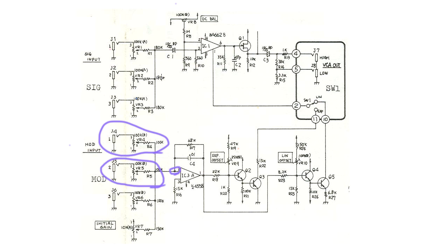I don't get weird effects such as the input impedance seen at J1 changing depending on what's happening at J2, etc. If you did want to think about what the impedance was, it would be whatever the impedance of the upper branch of the pot is, plus whatever the impedance of the lower branch is in parallel with this 100K input resistor. It would be interesting to make a plot of how that input impedance changed as you sweep the knob, but I won't worry about that here.